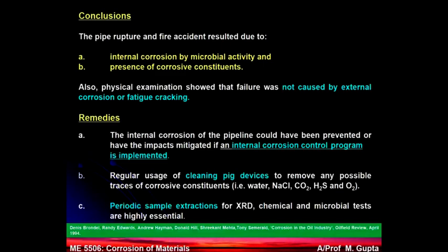What really happened is that these microbes came in with a fluid, they settled, they made colonies, and when they enter into biological activities, because they are living organisms, they create a corrosive environment. Then they start eating the pipe wherever they are deposited. The pits are formed, and these pits slowly grow, and then the thickness of the pipe is compromised, pressure is there, there is stress concentration, and it's an over-stress failure.